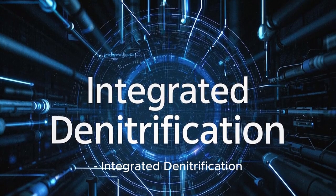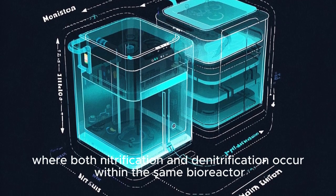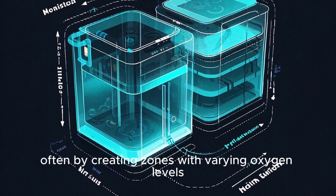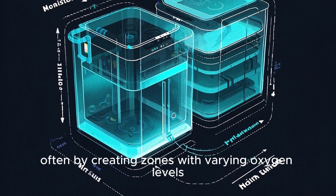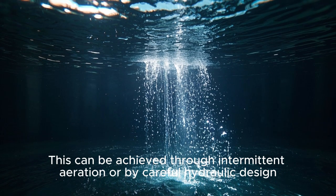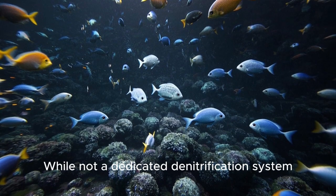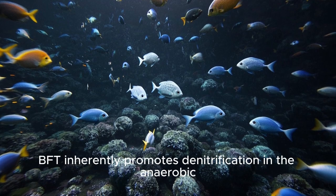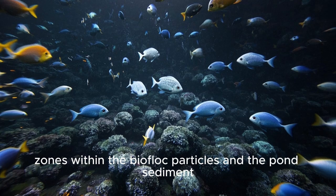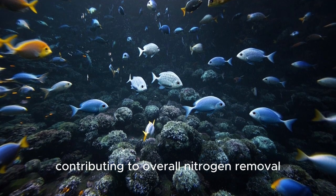Integrated denitrification. Some RAS designs aim for single sludge systems, where both nitrification and denitrification occur within the same bioreactor, often by creating zones with varying oxygen levels. This can be achieved through intermittent aeration or by careful hydraulic design. Biofloc technology, BFT. While not a dedicated denitrification system, BFT inherently promotes denitrification in the anaerobic zones within the biofloc particles and the pond sediment, contributing to overall nitrogen removal.